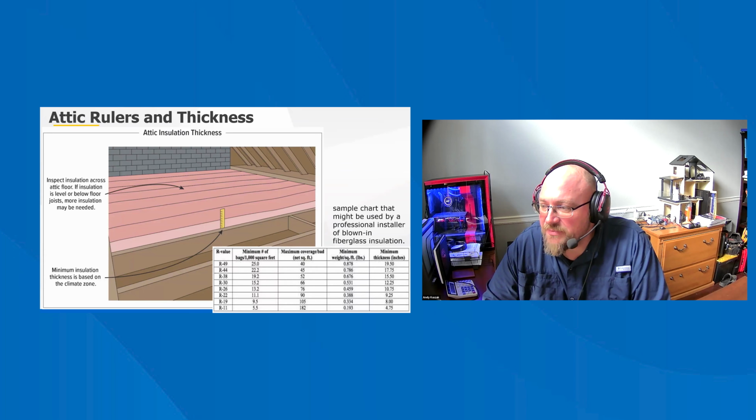The recessed lights should be properly filled in and covered. Insulation contact rated fixtures: only IC rated recessed lights should be installed because they are airtight and could be covered with insulation. Check underneath any pieces of plywood or platforms in the attic. Those areas need to be insulated. If mechanical equipment or storage areas are located in the attic, the flooring or platform decking should be elevated to allow full height or thickness of the insulation to be installed. Check around ductwork, wires, and plumbing.